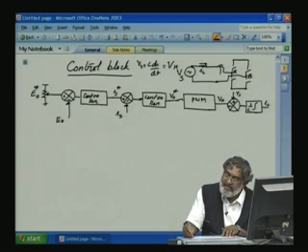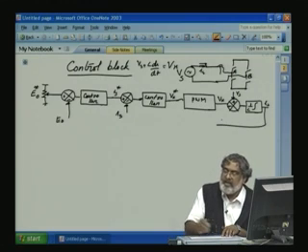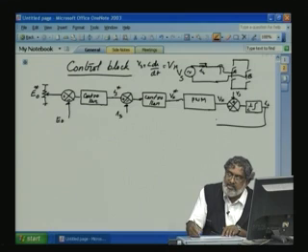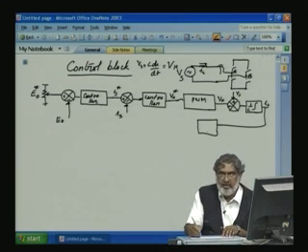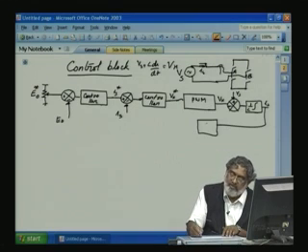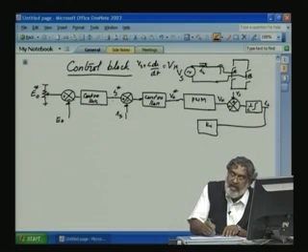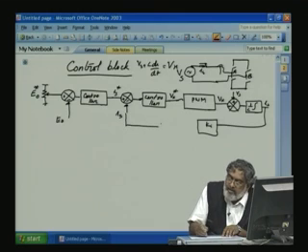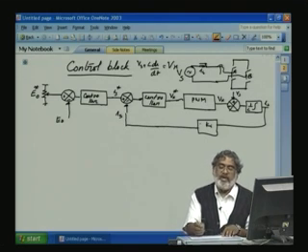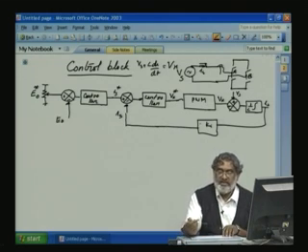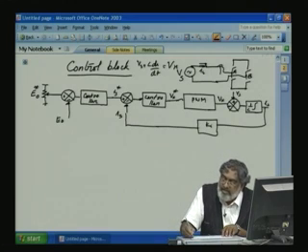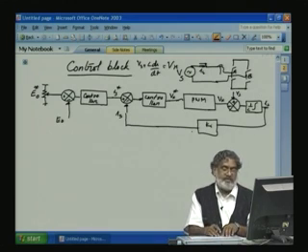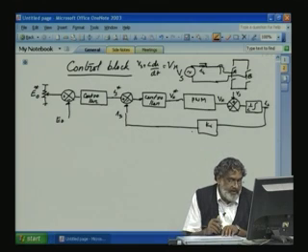These are actual currents, we have to bring it to the controller side. So, we may require a gain function to reduce it, or if you want to filter it, a filter will also be there. We will put a simple gain function Ki, the current gain. So, that is the reference and Is. If the controller is built using analog controllers, maybe the signal can vary only up to plus or minus 10. So, when we sense the actual current and bring it back, a gain function is required. This is how you do it.